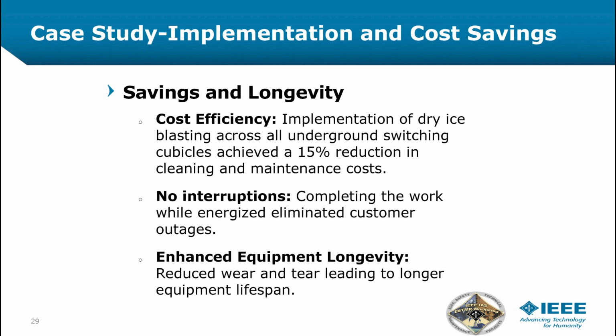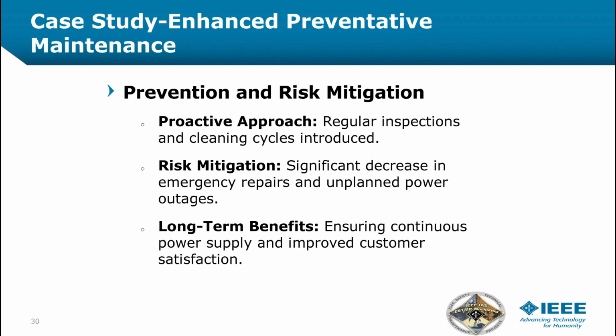Implementation of dry ice blasting across underground switching cubicles achieved a 15% reduction in the cleaning and maintenance costs. No interruptions. Completing this work while energized eliminated customer outages and enhanced equipment longevity, reducing wear and tear, leading to longer equipment lifespan. Prevention and risk mitigation.